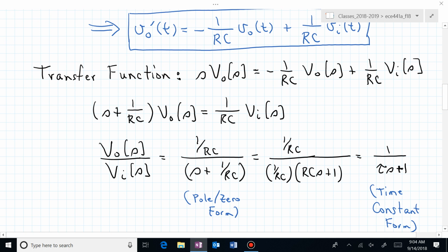Finding the transfer function is simplified because we don't have to worry about initial conditions when we Laplace transform derivatives. That allows us then to immediately write down the frequency domain expression connecting the voltage of the capacitor, which we're viewing as our output voltage, and the input voltage that was supplied to that first order circuit.